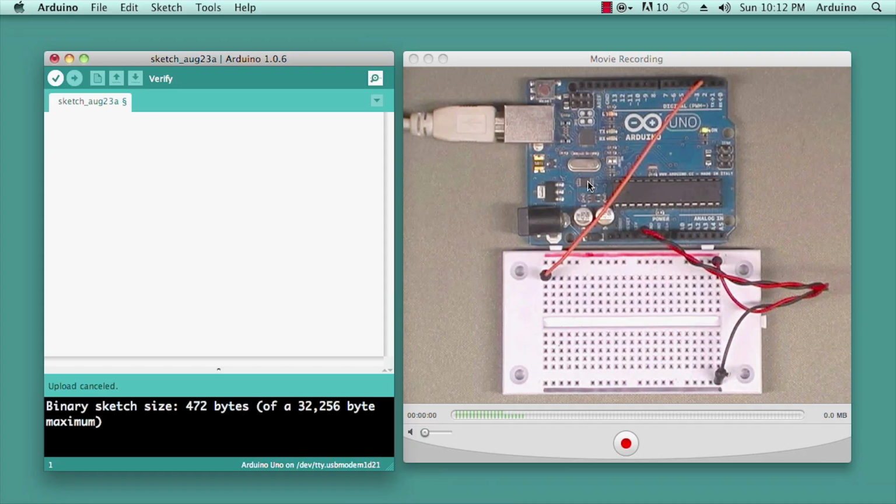So we need some way for the Arduino to communicate back to our host computer while the program is running. And that, of course, is going to be through the serial monitor. Remember, I told you that one of the things the serial monitor can be used for is to pull information off of the Arduino while the program is running. So we're going to start with our two favorite functions, void setup, and you should know all this by rote now, and void loop.